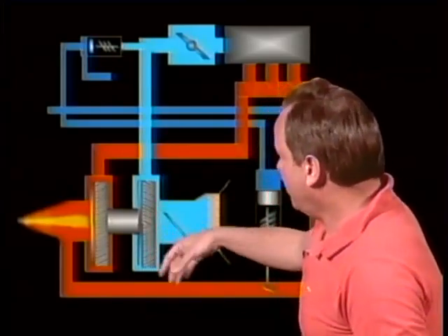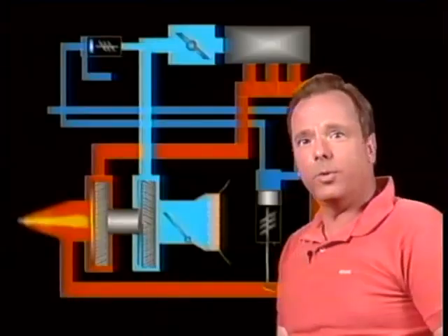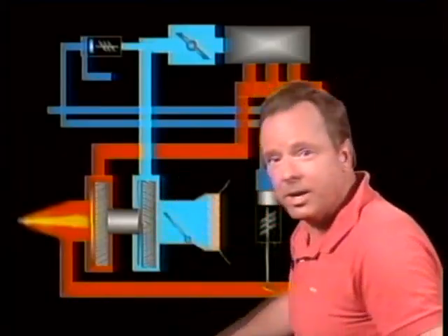impeller. And if you don't want to supercharge a lot, you'll select low-speed impeller, and if you want to supercharge an awful lot, put a lot of increased manifold pressure there, you'd use then high impeller in that particular case.